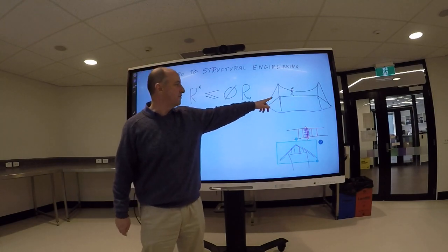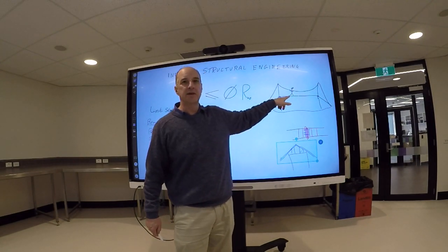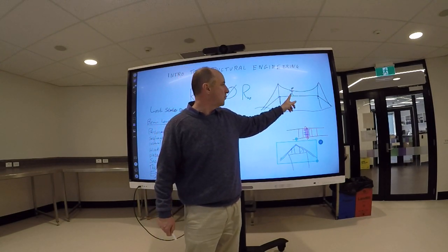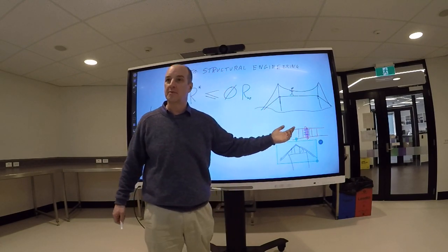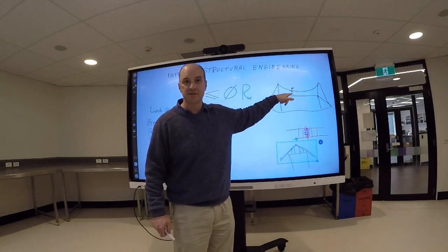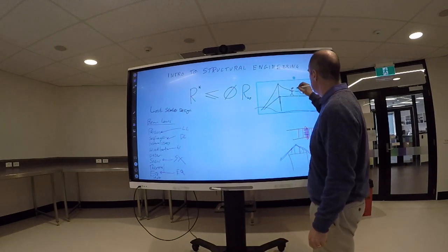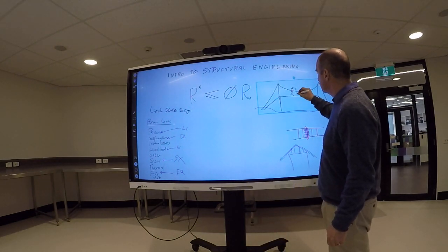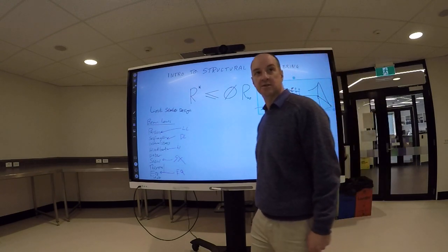If you look up AS 1170 for a bridge, like a suspension bridge like this, it'll be 1 person, 1 kilonewton per meter length of it, if it's a single file type bridge. That's not a figure that everyone carries around in their head. I just happen to be designing one a bit like this at the moment. So theoretically a person could be there, another person a meter away, another person there, and the bridge gets loaded up.